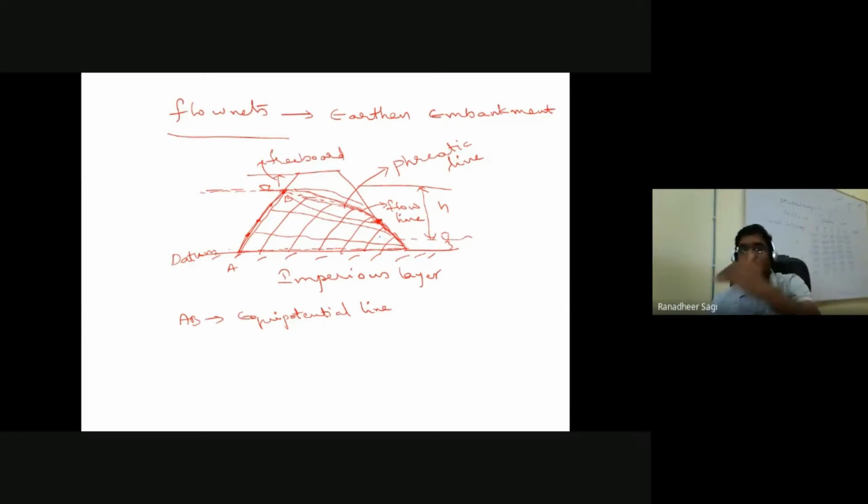If the water starts flowing, then there is a possibility that soil particles on the sloping surface towards the downstream will start getting displaced away from that location because of the erosion due to the water flowing along that downstream sloping surface. So once there is erosion, over time the soil in this particular region will certainly have an issue in terms of its stability. The particles will start moving out from this region, and automatically the stability of this embankment is going to be an issue.